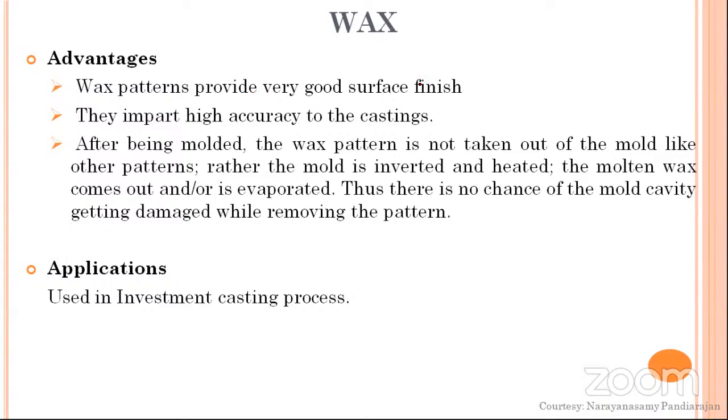If you have any questions, you can just keep typing them. Okay, somebody is asking, should we use a metal with a higher melting point than the molten metal? Not exactly. See, we are not preparing a metal mold right now. We are just looking into sand casting. So the metal pattern can be anything. It need not be a material which has a higher melting point than the casting material.